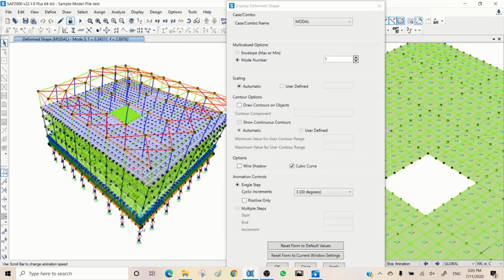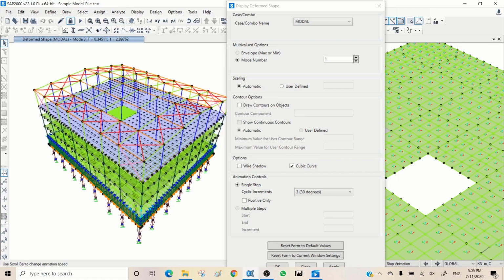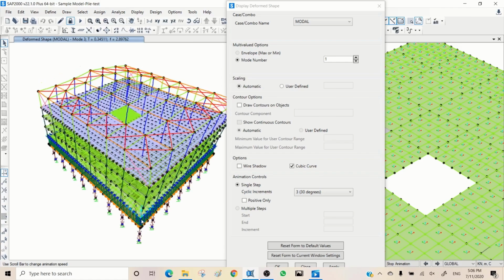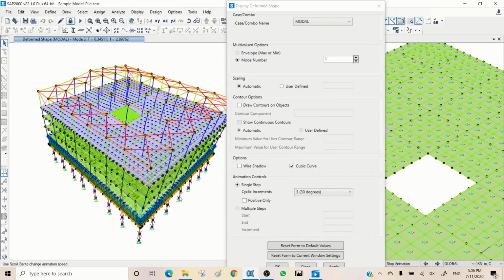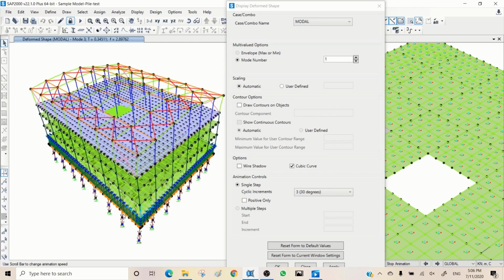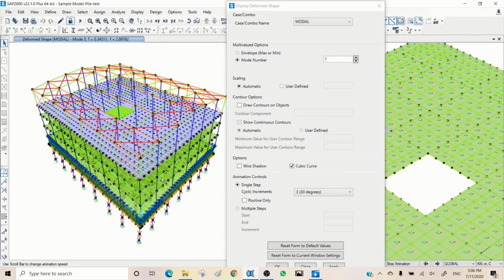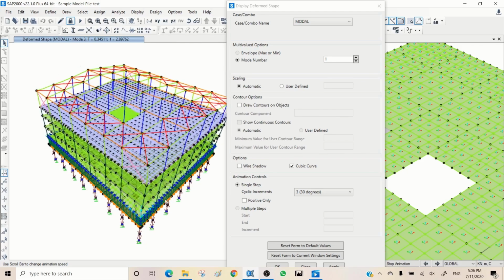So it doesn't matter even if you put your lateral support here at the ground floor or at the foundation level, because this box with the ground floor slab and retaining wall around and foundations below is very stiff, and actually the structure is vibrating from ground floor above, which is correct, which is what we expect. But when you had a spring around, it depends on the stiffness of the soil, it could be variable. It's really back to the sensitivity of the structure and the importance of the structure, that if you want to have a full model in modal analysis and response spectrum analysis, or you want to use it based on the base level of the earthquake.